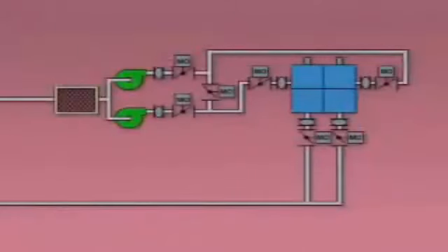Here's another type of once-through circulating water system. In this arrangement, there's a circulating water pump for each water box. A cross-connect or tie valve in the piping can be positioned so that flow through both halves of the condenser can continue even if one of the pumps is shut down. This arrangement allows the turbine to continue to operate even though its load may have to be reduced.